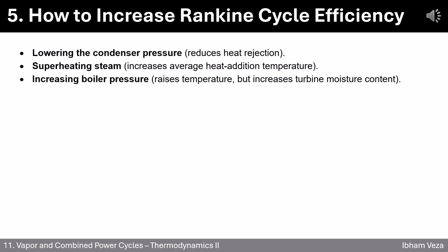However, there's a trade-off. Doing this can increase the moisture content in the steam leaving the turbine, which can harm turbine blades if not managed properly. The key takeaway here is efficiency improvements often involve balancing trade-offs between performance gains and equipment limitations.